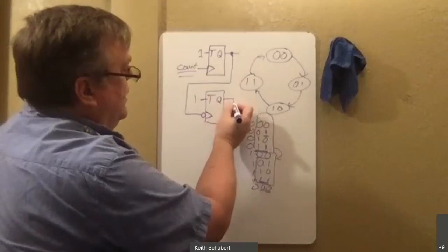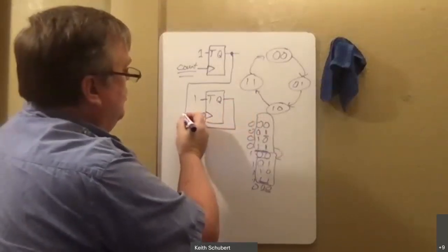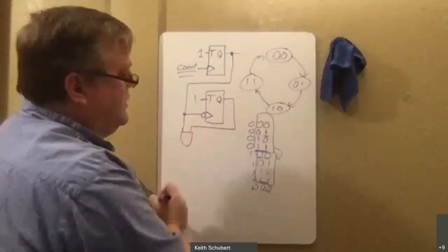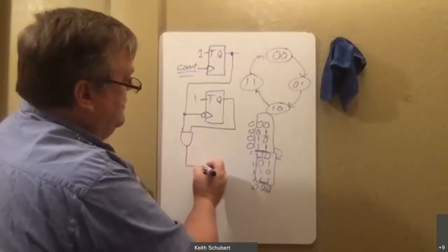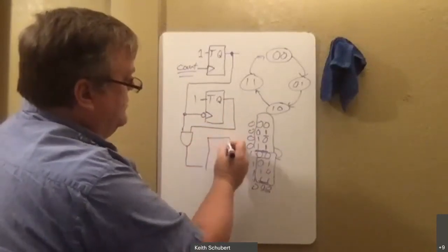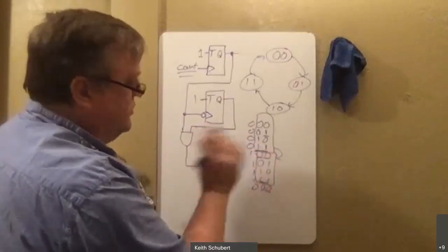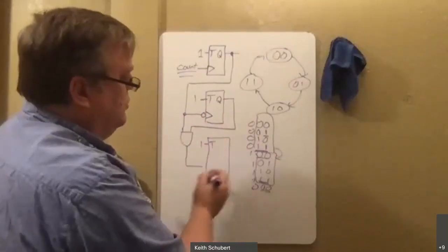So now what I want to do is take this clock when they're both 1, I just AND them together. If they're both 1, I'm going to take that to my next layer. I'm going to want to toggle because it goes from 0 to 1 or 1 to 0 in that case. So that is again a toggle. You just turn it on.